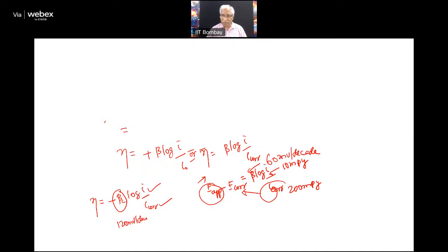The sacrificial anodes are used to protect the structures. The sacrificial anodes dissolve and then they deliver the current to the structures. So the current is derived from the dissolution of the sacrificial anode.